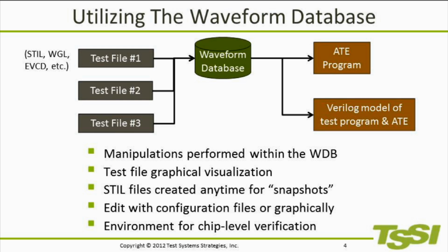The TSSI full chip pattern integration approach utilizes a database. The input test files are converted into the waveform database. This makes data manipulations easier and minimizes errors. The test data is more easily visualized with graphical tools instead of using a text editor such as Vi or Emacs.